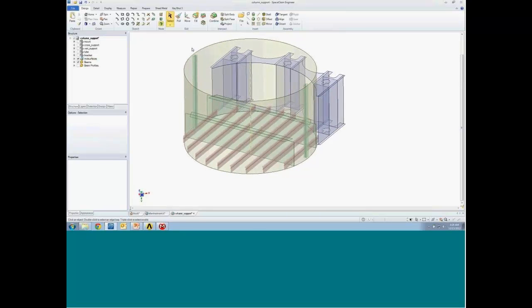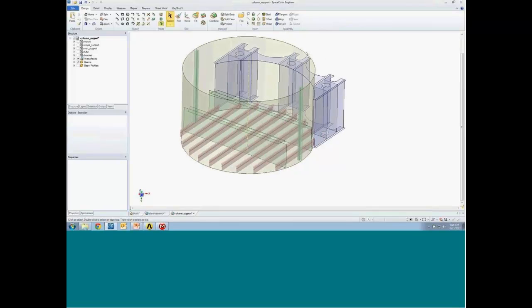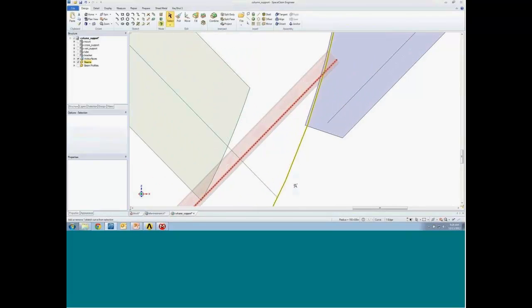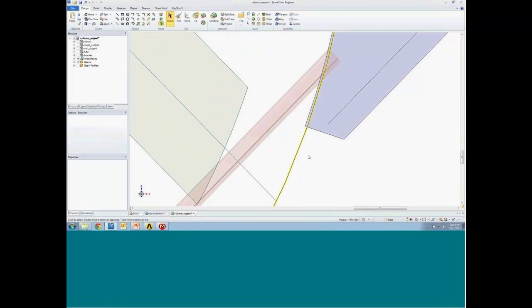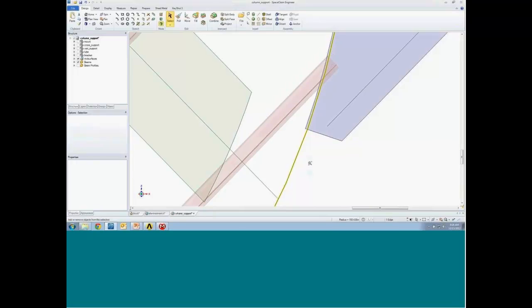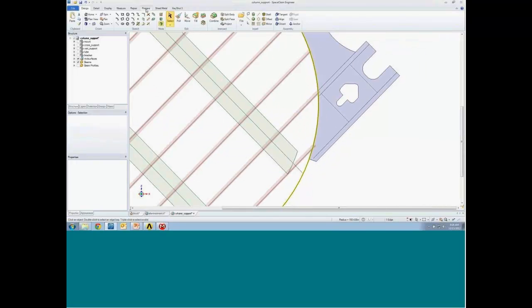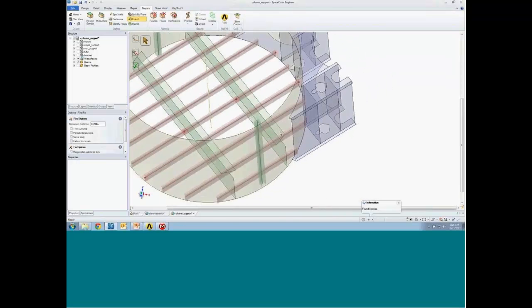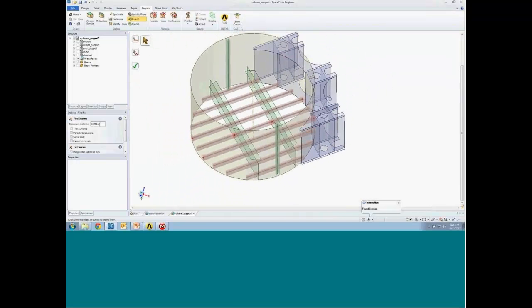All right. So how do you correct all the edges? And you guys probably know what I mean, but I'll just zoom in and show you exactly what I'm talking about. The mid-surfaces obviously don't touch. You don't get an edged face connection. Well, within this Prepare tab, there is an Extend tool. I click on Extend, and there's a number of options to change. One, namely, would be changing the maximum distance for which I want to search everything. So let's just crank it up to 4 inches.